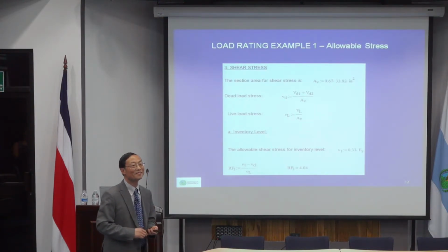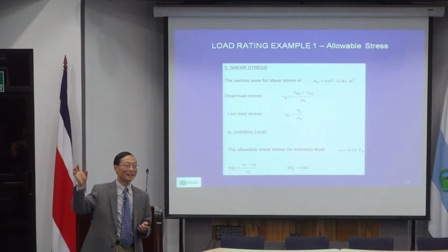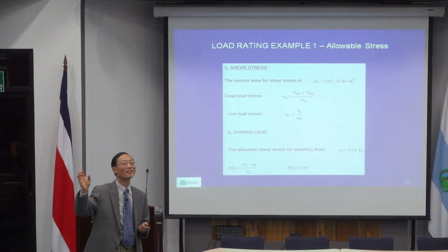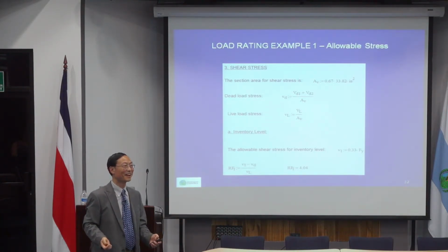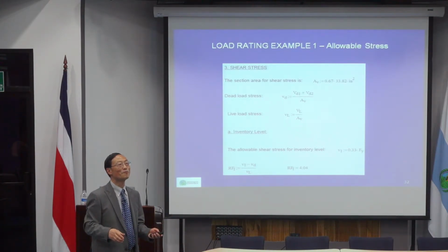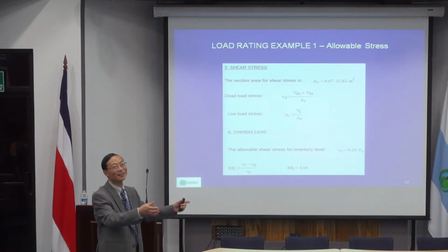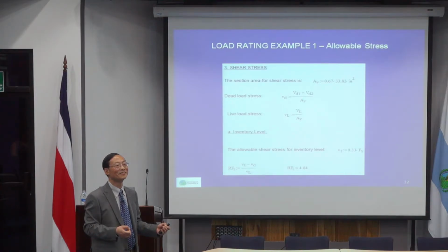No, actually, that's an advantage of doing calculation manually. If you do calculation by computer, it will rate every element and every location and every force. In other words, each element calculates bending, shear and so on. So the computer has the advantage of fast calculations, it can calculate everywhere, then select the worst situation. But for manual calculation, you have to make judgment, just by looking at what may be the most critical element and what location may be most critical.